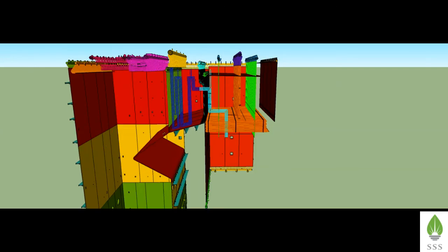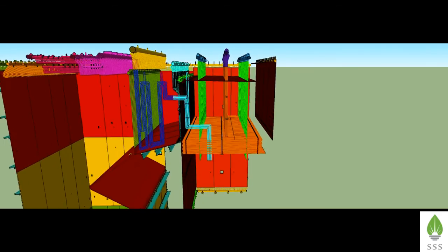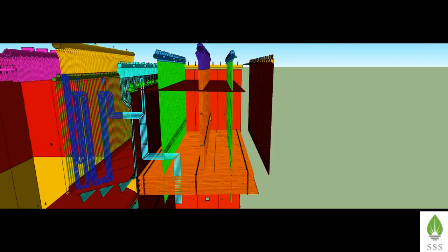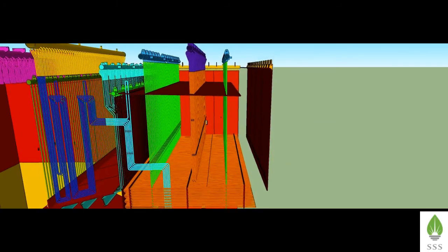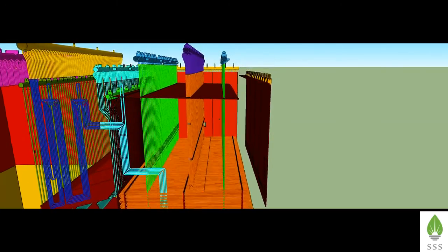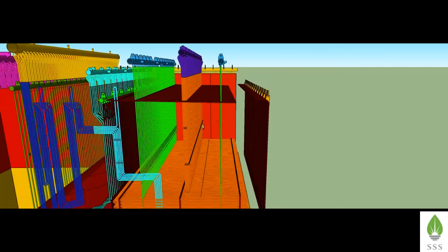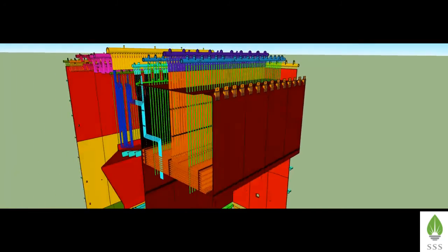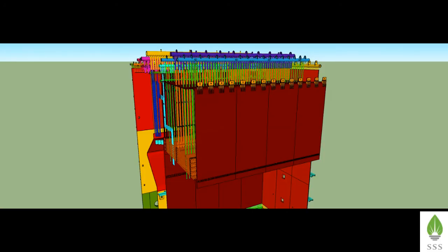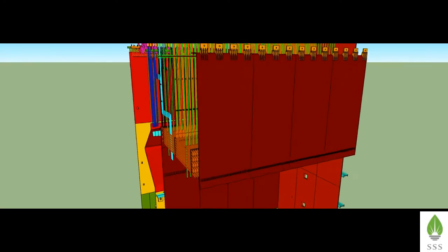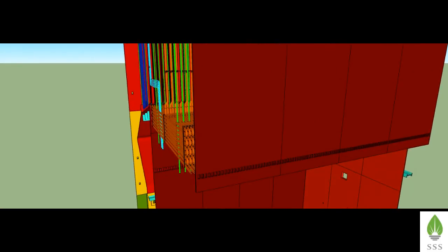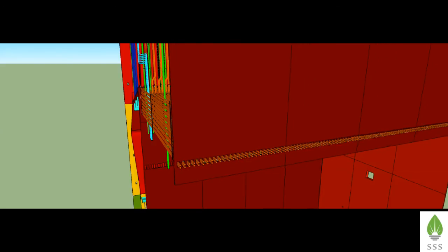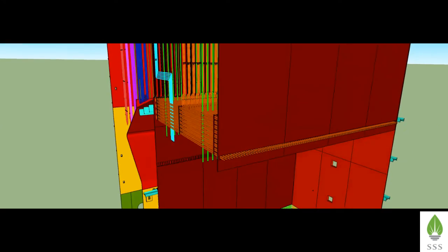Cage rear wall top panel was laced with the boiler structure previously. Now the same shall be brought to its position after complete erection of primary superheater horizontal coils. The cage rear wall top panel shall be released from chain block and moved to its position slowly. The primary superheater horizontal coils protrude through the fin openings provided on the cage rear wall top panel. Move the panel slowly in horizontal direction and weld this panel with one end of cage roof panel.